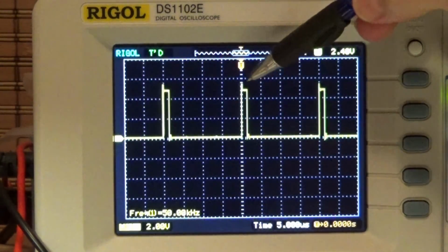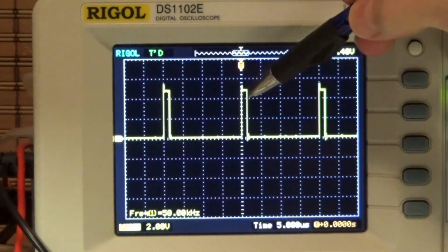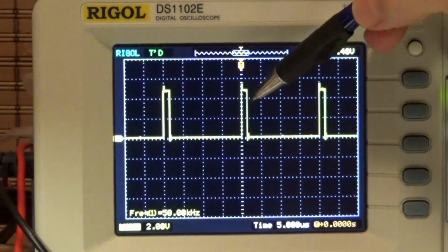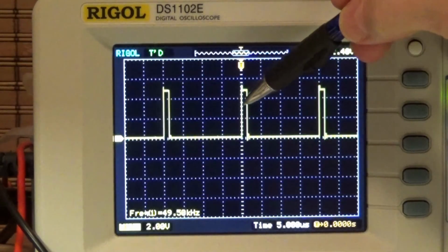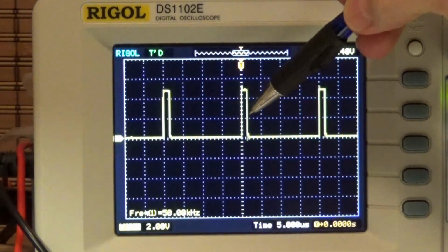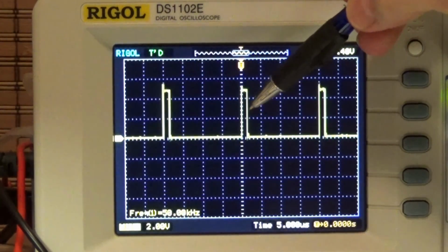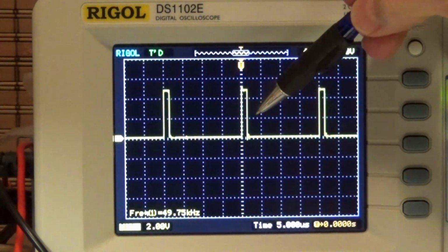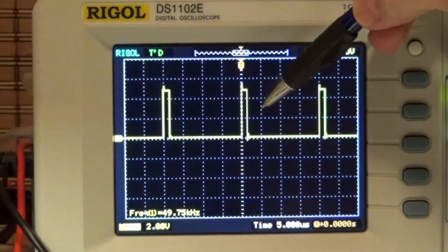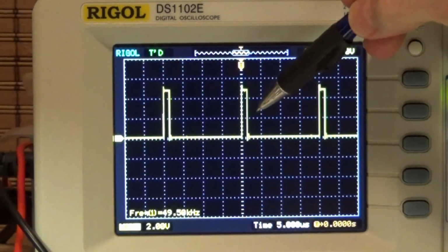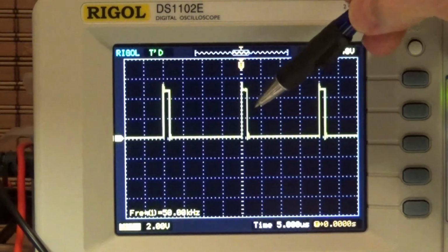And then we look, and so the time in between when this line goes high and it goes low is when it's actually processing the interrupt. Actually, the timing is going to be a bit longer, because it takes the processor some time to go into the interrupt service routine, and then when it leaves the interrupt service routine and gets back into the main code, which in this case is doing nothing but sitting in a while loop, it takes a couple extra cycles as well.